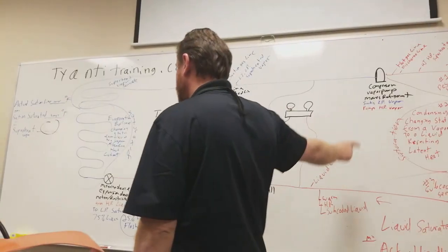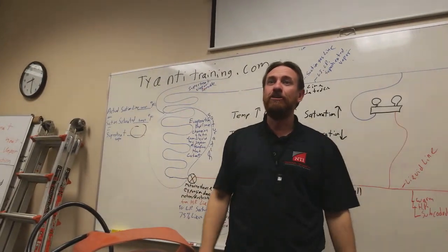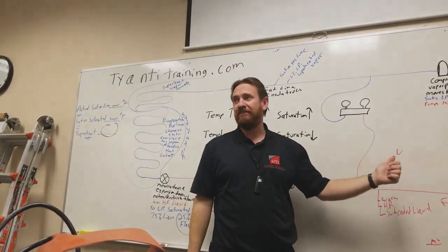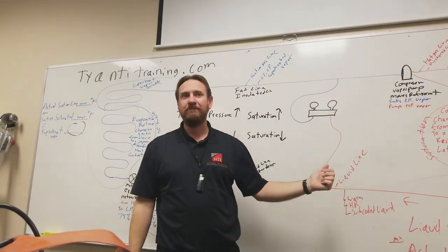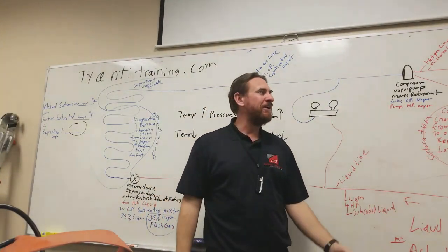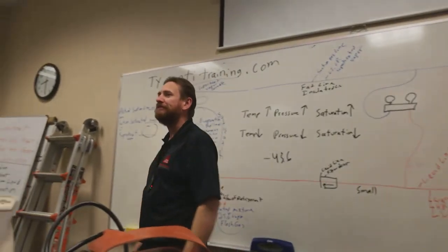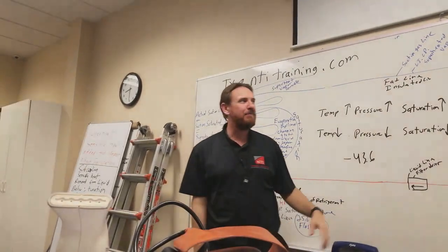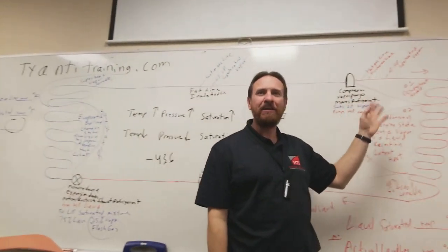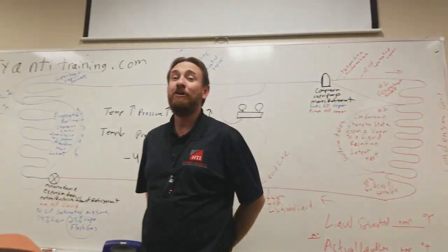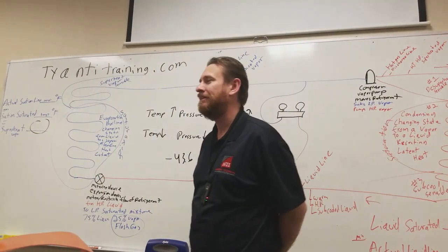Should there be oxygen inside this refrigeration system? No. There should be refrigerant and refrigerant oil. Never oxygen. So if I don't have oxygen inside this system, can I have an explosion? No. Even if I pressurize the propane, without oxygen, can I have an explosion? No, I cannot. I cannot have an explosion without oxygen.